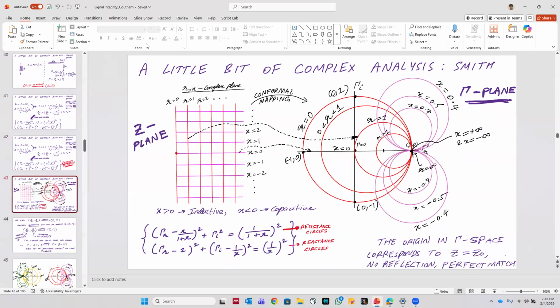So here's what it actually looks like. Let's say this is the Z plane, the impedance plane. These red lines represent different values of resistance. These are normalized to Z naught, so R equals 0, 1, 2, 3. And the reactances are on the y-axis, so X equals 1, 2, 3 positive and X equals minus 1, 2, 3 negative, positive reactance and negative reactance. Why is the left half of the plane empty? Why haven't I considered that? Negative resistances? Exactly. You can't have negative resistance, so it's only the right half of the plane.